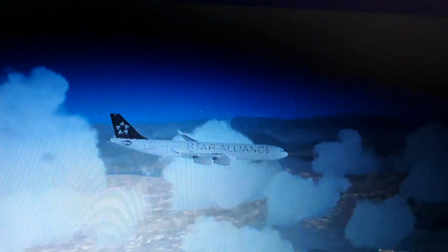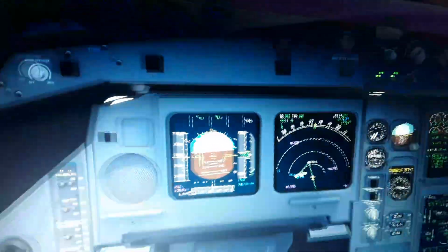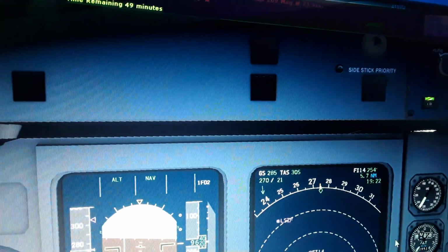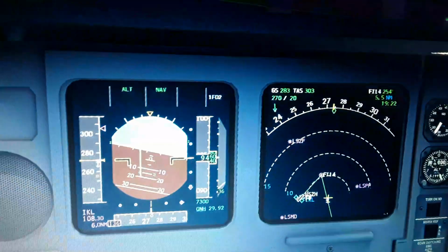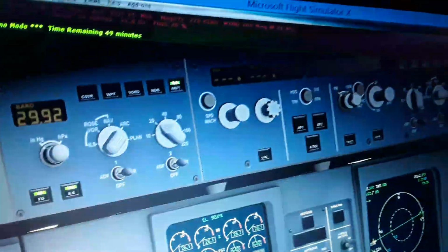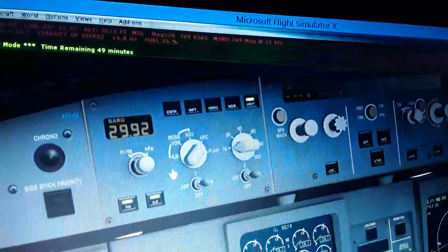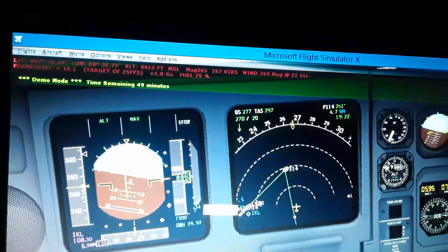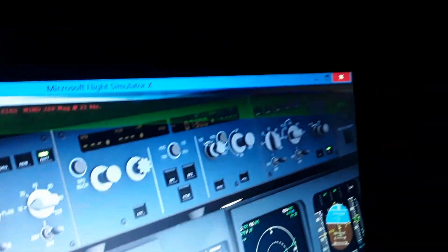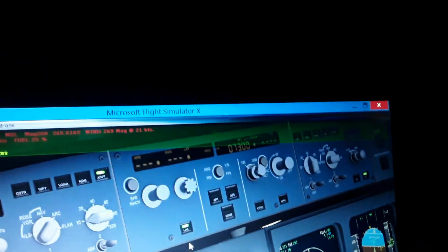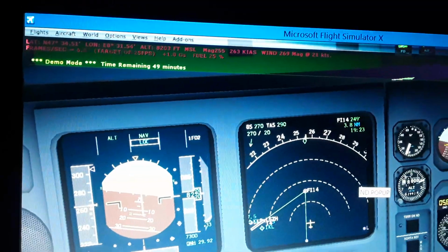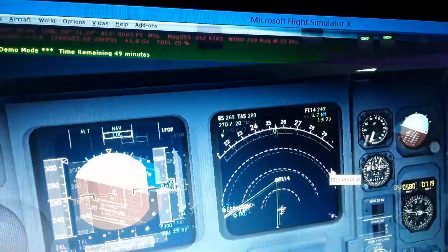So maybe extend the speed brakes in a while. I'm extending the landing gear. Use shorter range for that. Have a much better view like that. So we have the ILS on. We need to use the localizer to tune us in, which is gonna line up with the runway heading. So here we are crossing 8,000 feet.